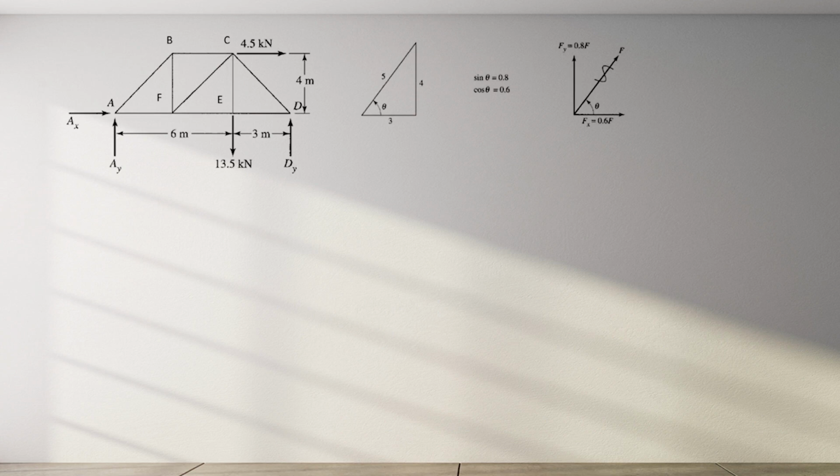We have our truss and free body diagram. Use joint A as the starting point, because we know that we only have two unknowns in joint A, which are the forces FAB and FAF. Start by drawing a free body diagram for the joint. Find the x and y components for every force.